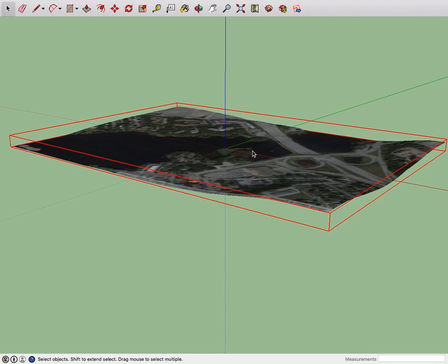So I would take that GIS file or that GIS AutoCAD contour of the water's edge, and then just extrude it down into whatever it is, like 2 meters, 3 meters, so that you hit the water and cut through that, and then just join that whole model, like Boolean the entire model into one closed polysurface. That's probably going to be your best bet, so that you still have that flat dock that goes straight down into the water.